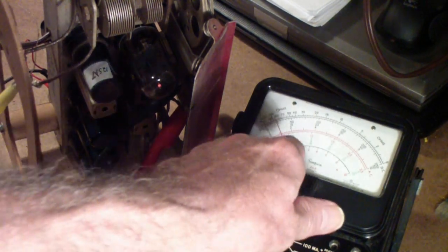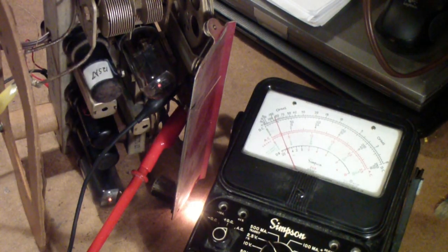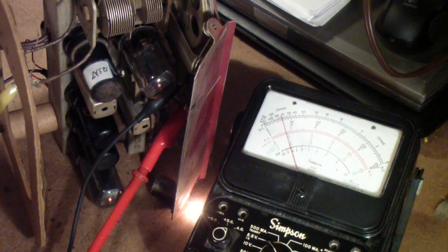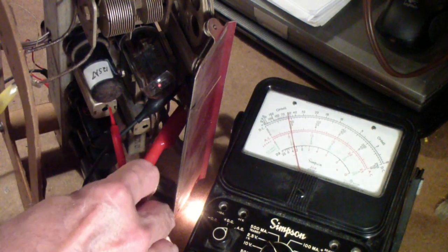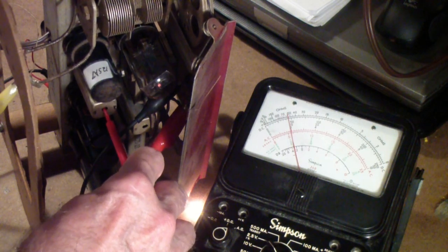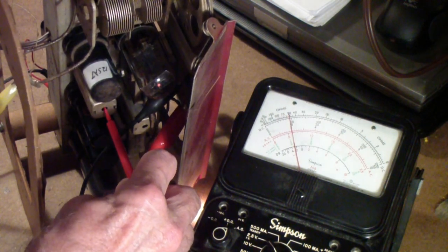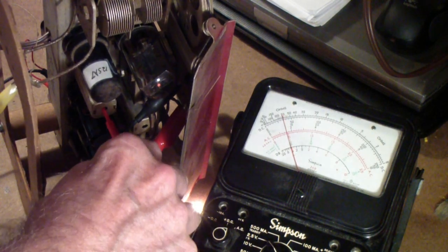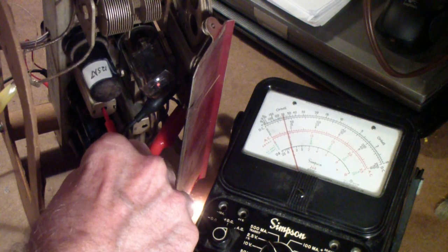And you see the meter is reading here. I'll explain a little of what I'm doing later, but first, pardon the high volume because it's necessary for what I'm doing here. I'm going to adjust this IF transformer. Notice the needle going down and the volume going down.